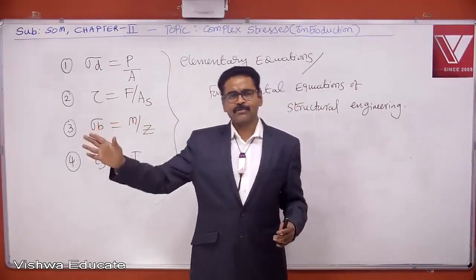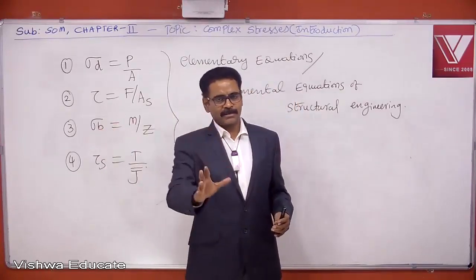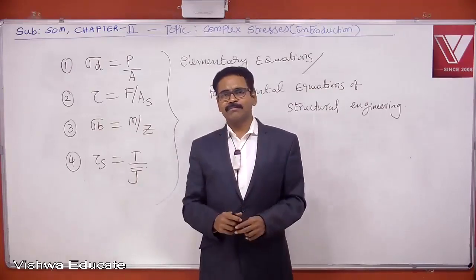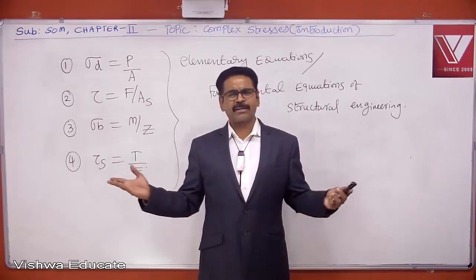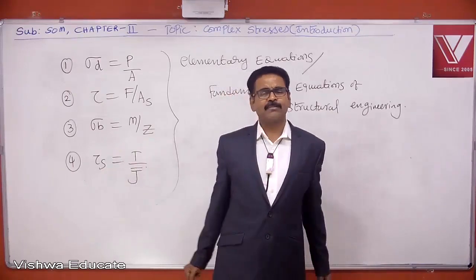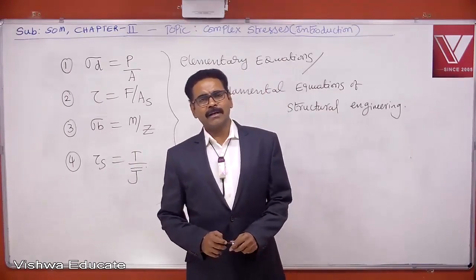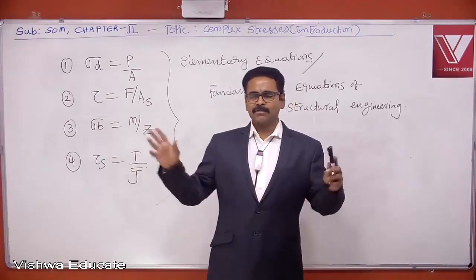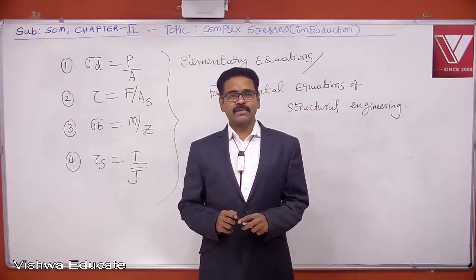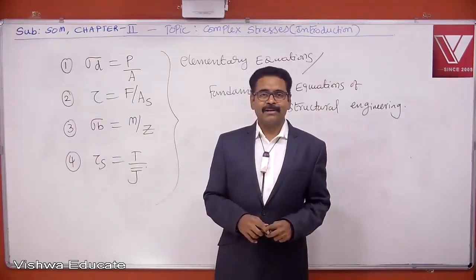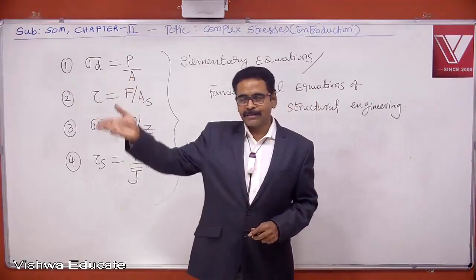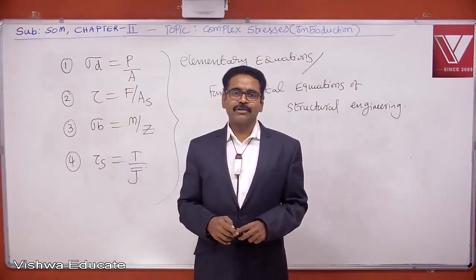Just observe those critical planes. In brittle structures, the critical plane is the major principal plane. In ductile structures, the critical plane is the shear plane. If these two planes are safe, the entire structure will be safe. If any crack forms, it will form about either the major principal plane or the shear plane.